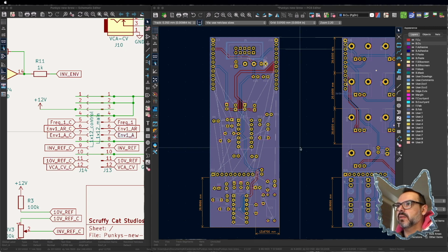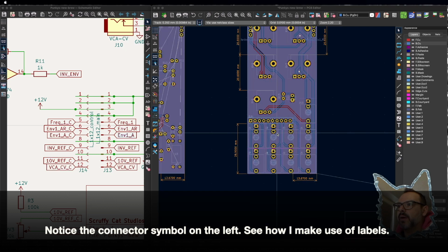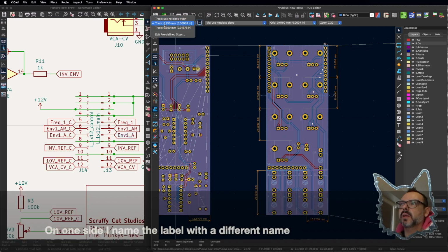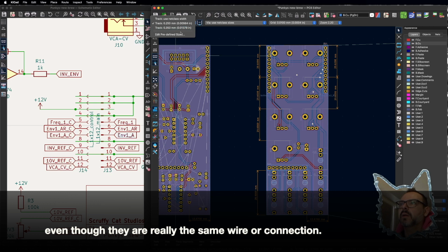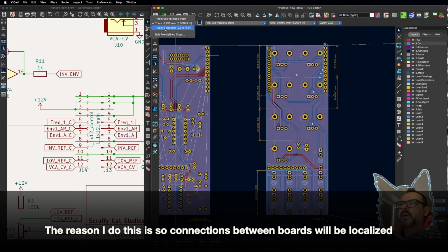But so I've added the ground fills. I switched around some of the ports just to make it more convenient on the control board, and I started routing the tracks. Okay, so what I've done is I've configured a few track widths right here, so I can select the track width in here easily.